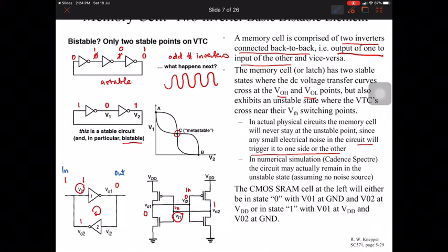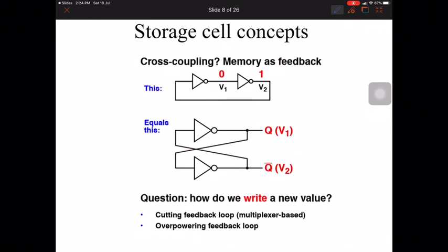So you can either store a 1 or vice versa. This is known as a memory cell. Those of you who are doing SRAM cells must know how the SRAM cell functions. It will always lock in a value and store the value in the back-to-back inverters.